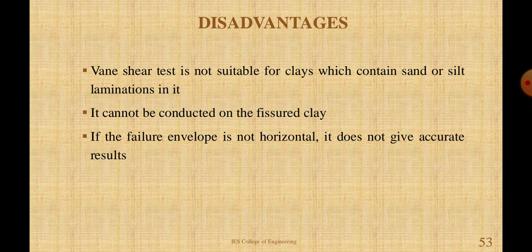Next, the disadvantages of Vane shear test. It is not suitable for clays which contain sand or silt laminations in it. It cannot be conducted on fissured clay. If the failure envelope is not horizontal, it does not give accurate results.